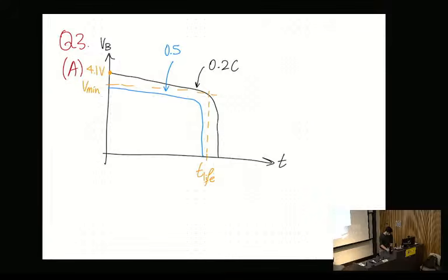So often when you're charging a battery, you charge it to C on 2, so half of its capacity. Charging and discharging rates are really important for lithium-ion to protect it. So often they get cheap chargers that are charging it at like 10 times the capacity, which it's not rated for. Cool. And also, this is important, I guess, for 3117 when you take it next year.